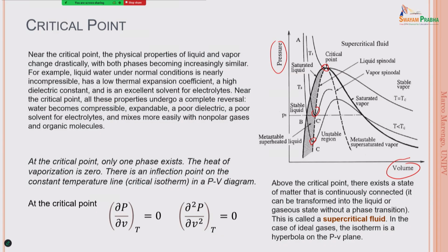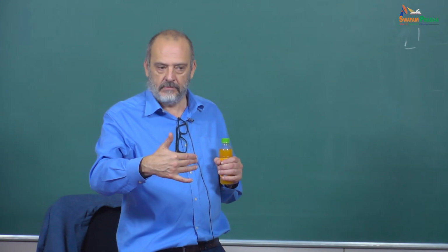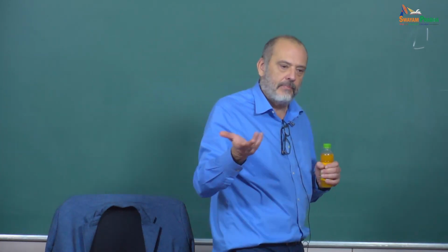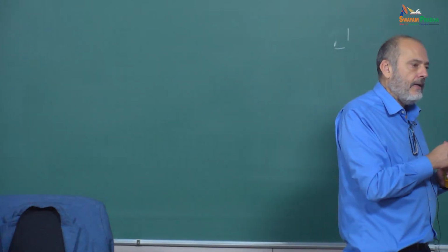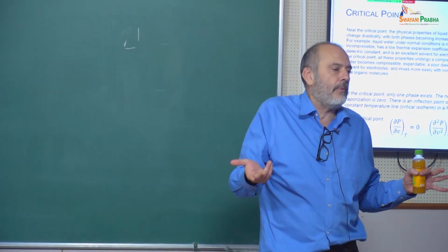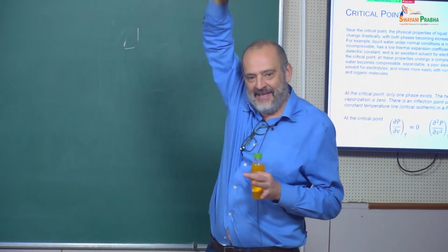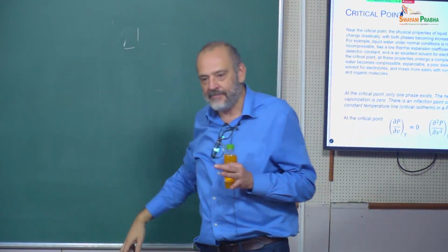This is very, very important because sometimes I saw, even in conferences from colleagues, incompressible simulations, using VOF, for example, an incompressible code, close to the critical point, 0.98, 0.97. I raised my hand. What is happening there? Are you sure?